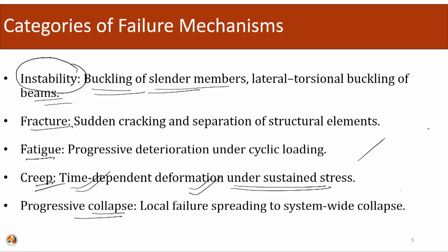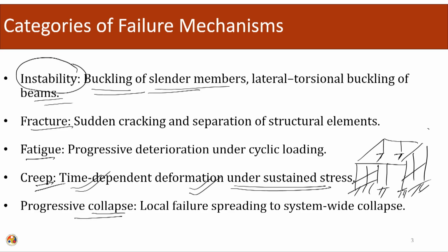So, let us say we have a framed system. We know that in a framed system there is a lot of redundancy inbuilt in the system. And we take advantage of this redundancy and we always optimize the section. So, if we have designed such that my sections are on the brink of an optimized configuration, all sections are loaded such that they are fully optimized, taking the maximum loading depending upon the capacity.